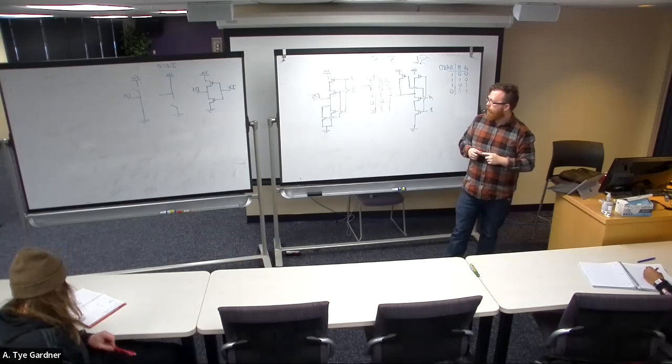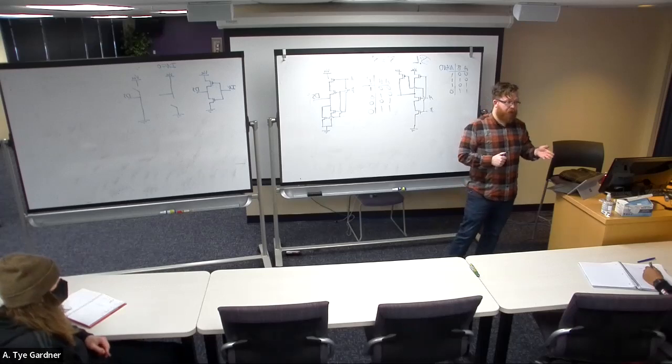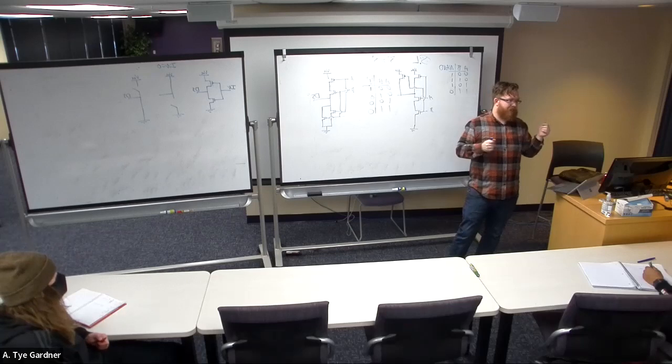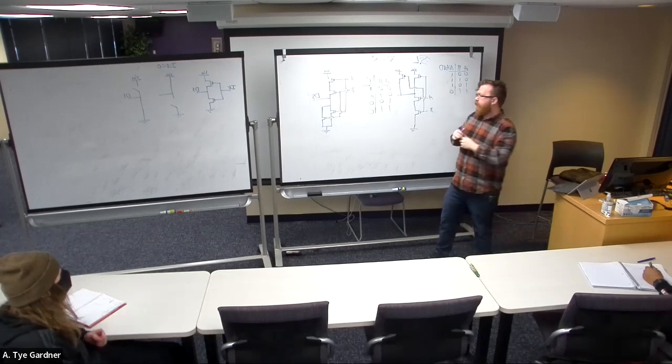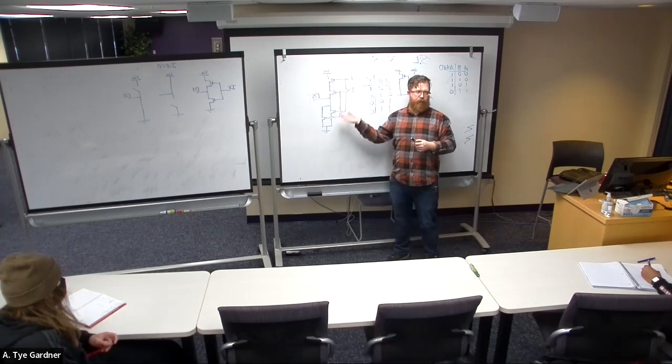Does the two NMOS on the bottom even matter? Because if either A or B is broken up top of NMOS, it wouldn't even get the signal from VCC, so it doesn't even need to be connected to ground. It does need to be connected to ground because otherwise it becomes floating, which means we don't know what it is. Okay. So if we only had one gate, then the A would make it a 0, but the B would make it